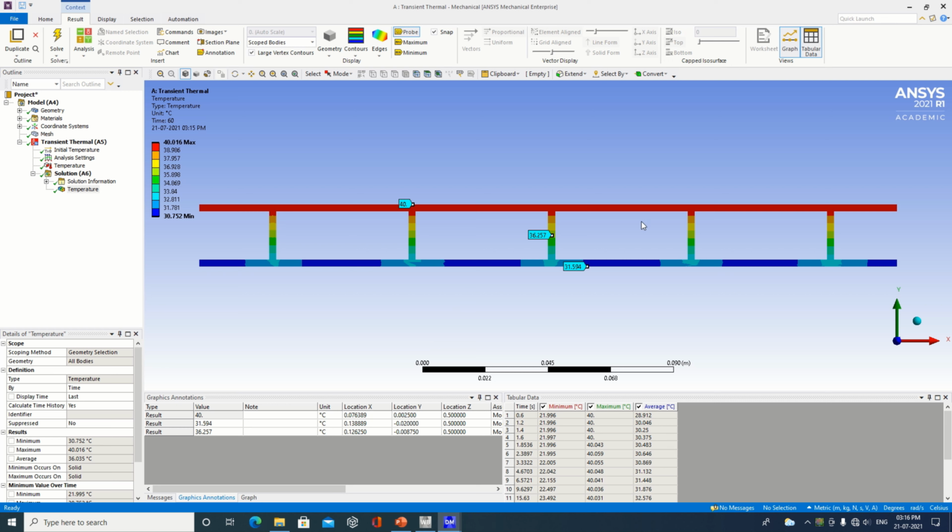If you change the shape to somewhat circular, in that case again you will transfer more amount of heat. So in this way we can do the analysis on the plate. I have shown you two examples. One is a single plate where the fin was connected, and the other I have shown with two plates which are connected, where the air will flow through this channel.